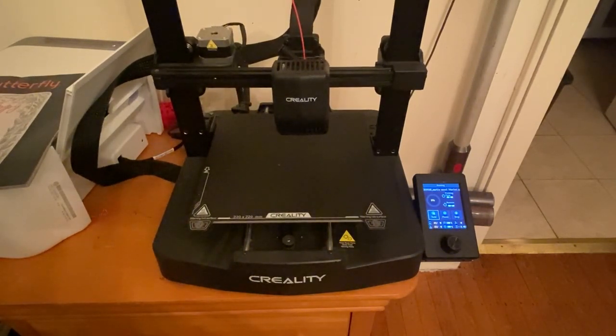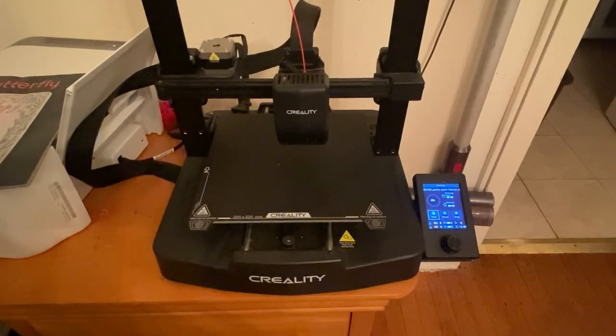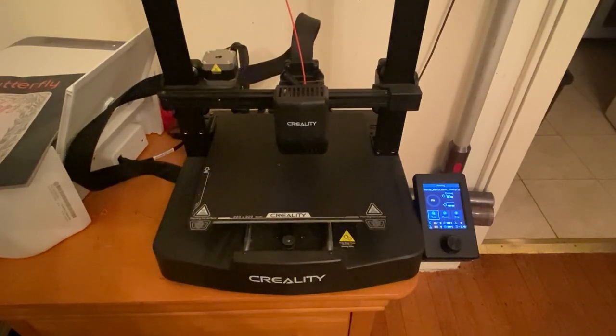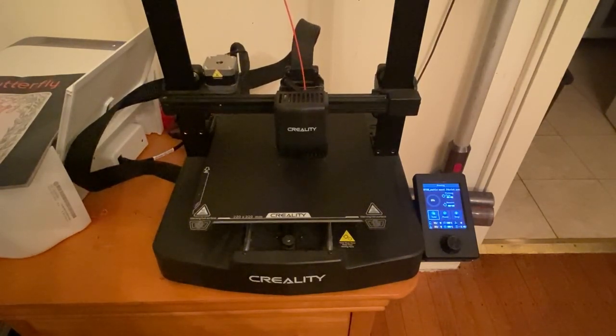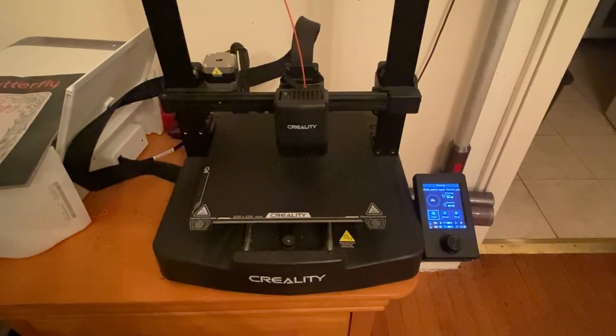But I would encourage you to stay around for maybe the first layer of your part just to make sure that it's successful. Because again, this doesn't really have any monitoring systems to tell the machine whether or not a print has failed. You're basically supposed to tell it to stop if it fails. Okay, so be aware of what the machine is doing, and you can leave once the first few layers are successful. Then you should be pretty confident that the rest of the layers are going to go smoothly.